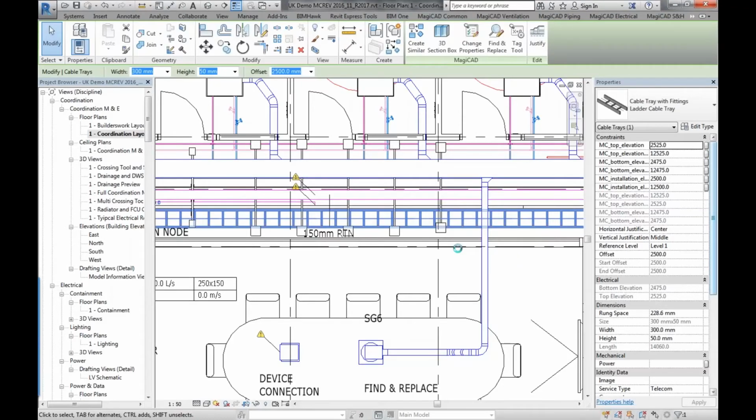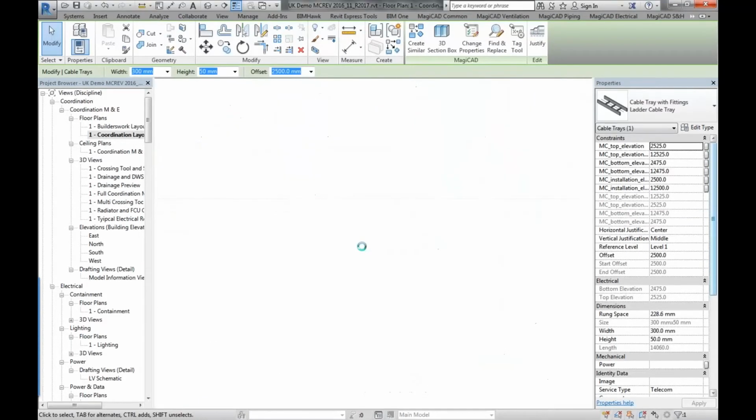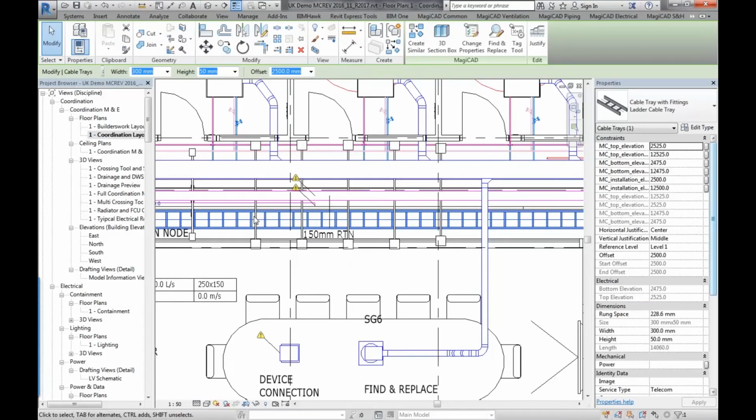You can see they've all moved now with the settings of the spacings remembered there. It's quite resource heavy. Sometimes you've got thousands of hangers attached to all different objects, so that's why we're giving you the option to turn that off. And if you do turn that off and then you want to update hangers periodically as you go through the project, then that's when you do update supporting hangers.